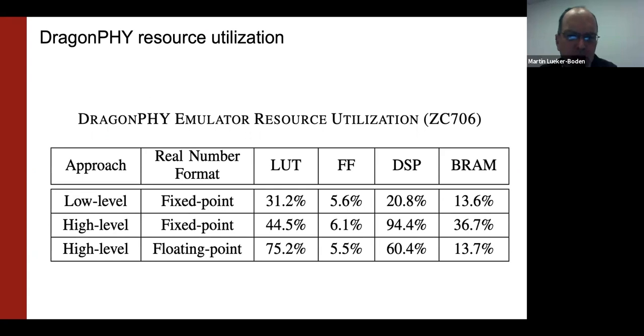And out of curiosity, for this one, did you have to massage your model a bit to make the fixed point model fit in the DSP resources? Was that challenging? Yeah, I did have to. I think I went through a couple of cycles on that. It's not very difficult to estimate the resource utilization, but it's also not automated. So I would have to make a guess of, okay, I think this is going to use about this many DSP slices, and then maybe iterate on that a little bit once. I see.